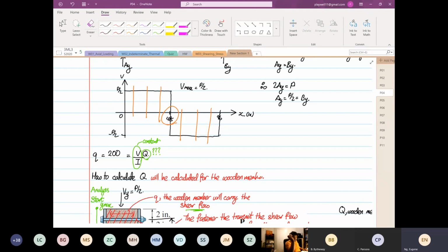So is it better to increase the spacing, or reduce the spacing, or is it better to use a bigger diameter bolt so it can hold? So there's a trade-off, yes or no? One is material cost, one is weight. Okay, so there's always a trade-off. That's where we do optimization, right? Wouldn't that increase stress concentrations if we put more holes into the wood? Yeah, right. It will increase stress concentration, but the fastener will still fail first.